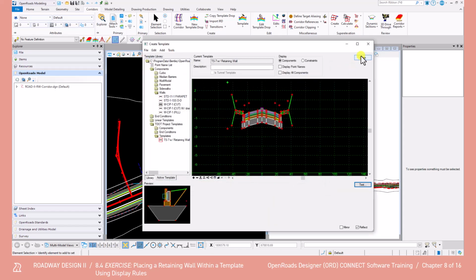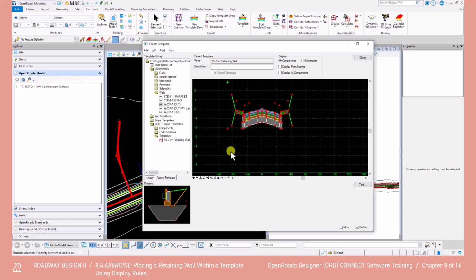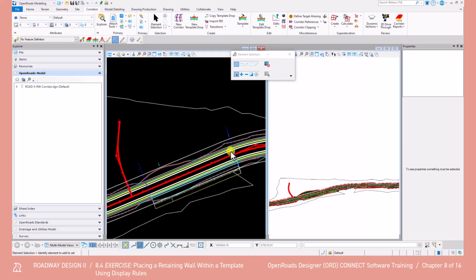Go ahead and close the Create Template window. When asked to make changes to the ITL, click Yes. And note that this will save changes to the default T.itl. It is recommended to delete these templates and any others saved during this training once completed with the manual. For an actual project, any ITL modification should be saved within the applicable project workset.